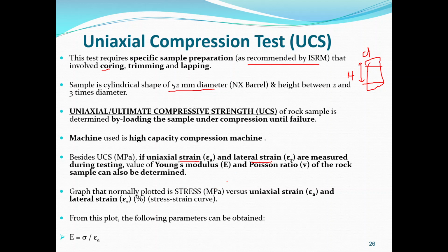But to get this strain, whether lateral or axial, we have to put some instruments, strain gauges, on our sample like this. So we have to put them in this direction for lateral strain, and here for axial strain.